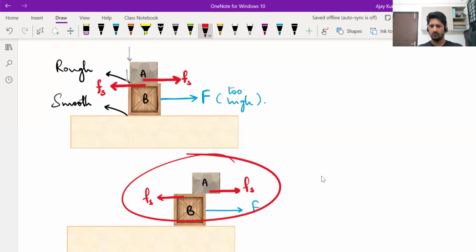No, sir. No. Okay. So even if a lot of friction is available, even if the roughness is more and friction available is more, that much friction will not act. How much ever is necessary to prevent sliding, that much only will act. That is why it is important to keep in mind that static friction is a self-adjusting force. The limiting value will not always act. How much is necessary to prevent sliding, that much only will act. So at best, it will make them go together.